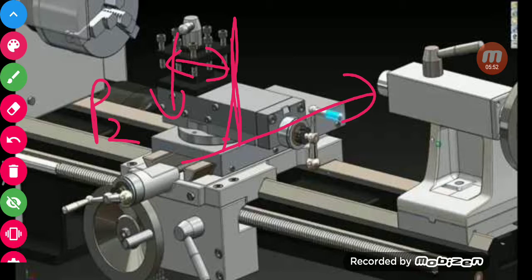In a bit we will go ahead and also see the two-dimensional diagram. Here I'm just giving you the quick visualization. There is another force, which is the force q, and we have discussed what q is. Q is essentially the force which drives the carriage ahead. This q also has a certain distance from the y-axis. There is a certain skew distance from the y-axis, and that distance has to be measured, and that would again create a moment. So that is the third one.